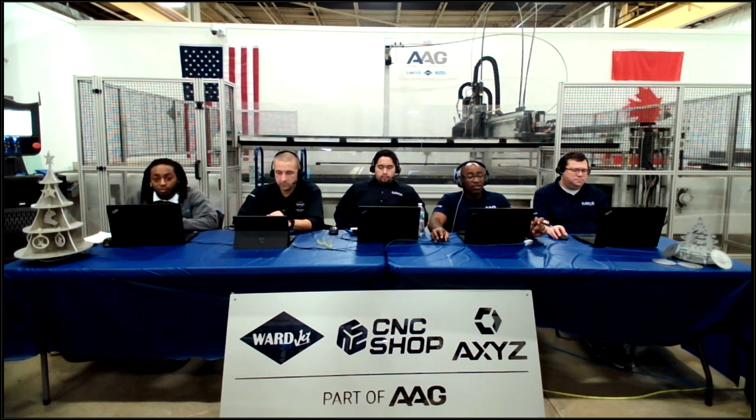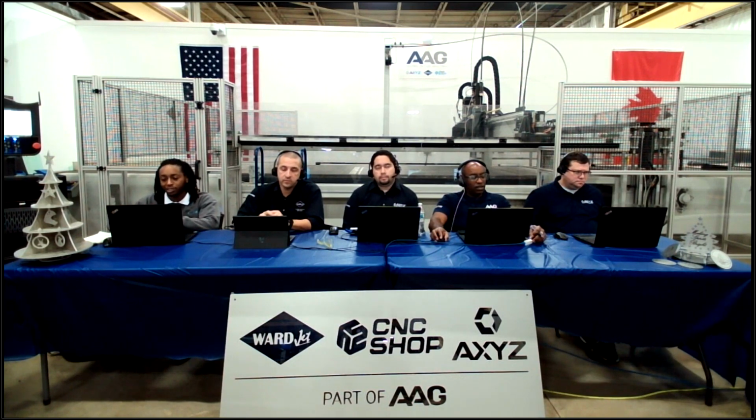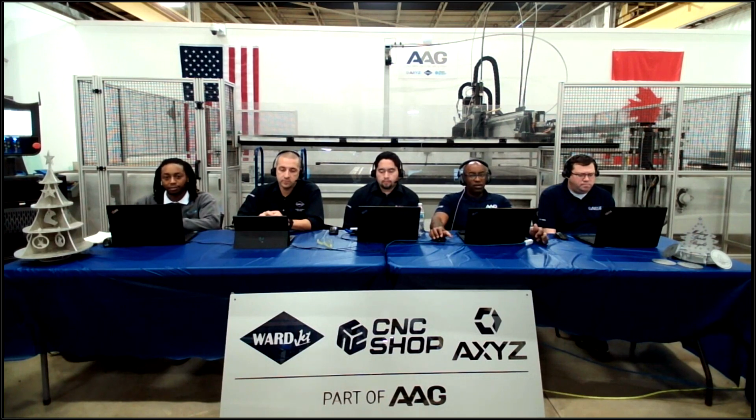So right now, if you want to run Fusion with our AXYZ router machines, there are relatively no limitations. It's just a matter of making sure that you're using the right post when operating our machines, and in addition to that, spending the time to make sure that you're selecting the correct tool path. Because oftentimes with Fusion, because there's so many options and you can get really granular with some of your selections, you tend to overlook some of the small details, such as ramping in, as Kevin was alluding to earlier.